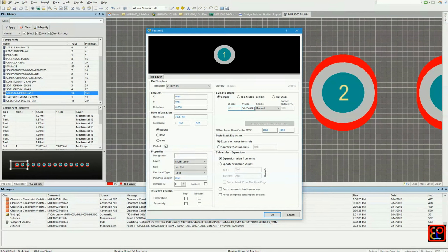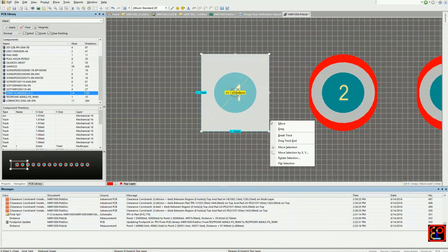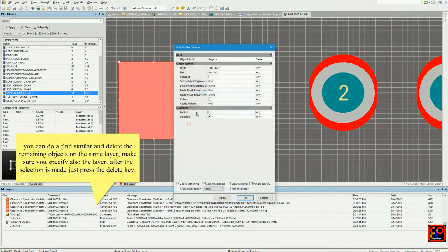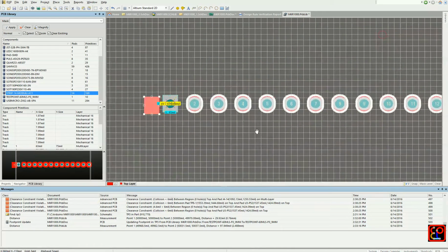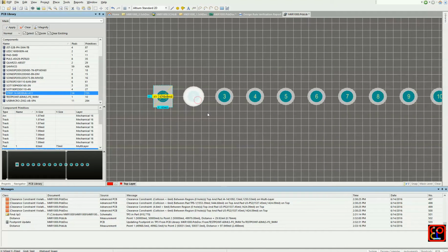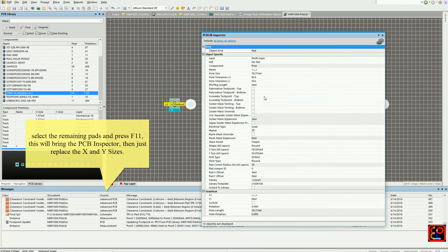So this shape didn't have any name or net list associated. When you open the PCB, those shapes didn't have any connections. The net is unknown. That's why you are getting a short between nets, where you have two different nets connecting together. So that's why we are getting the error. Just remove all the shapes and adjust the size of all the pads to match the shapes that were defined originally.